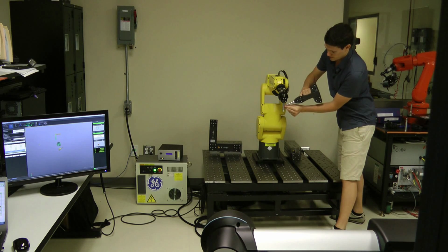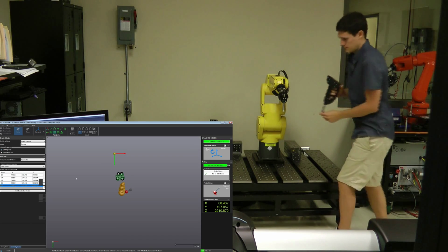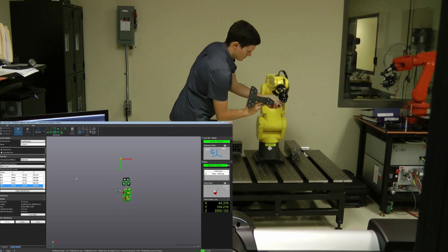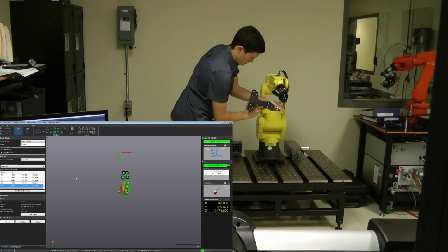For example, we can place the tool frame at the tip of a reference spindle. To do so, we must probe geometrical features that will define the tool axis and position. In this case, the geometry used as a reference is the cylindrical shape and the cone of the reference tool. When we're done probing, we can move the reference of the tool with respect to the geometry.